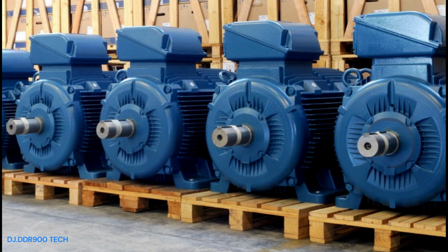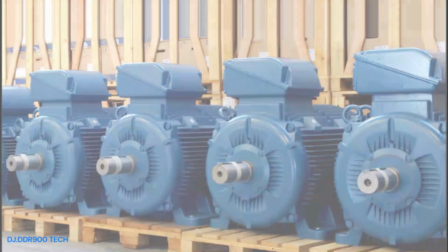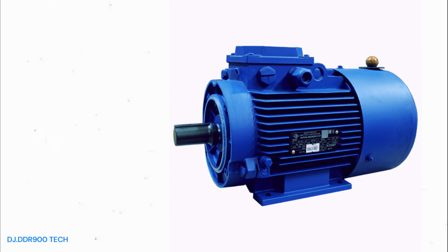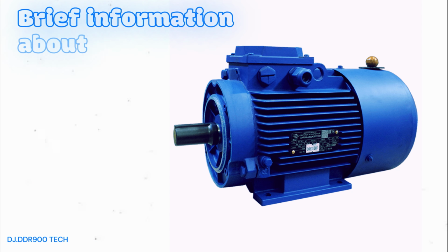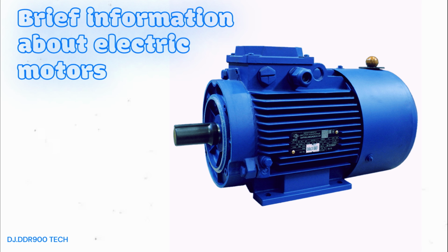There are many types of electric motors, differing in principle of operation, design, performance, and other features. Consider the main types of these electrical machines. According to the principle of operation, magneto-electric and hysteresis electric machines are distinguished. Despite the simplicity of design and high starting torque, the latter are not widely used. These motors have a high price and low power factor, limiting their application. The vast majority of manufactured electric motors are magneto-electric.